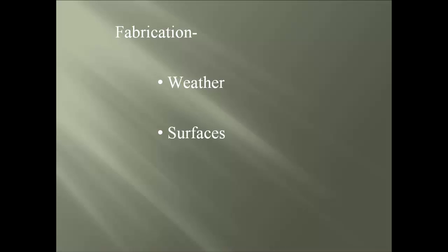Base metal surfaces are next, which should be free and smooth of cracks, tears, etc. that could affect the quality of the weld assembly. The third item is the joint, which should be arranged for the most favorable positions to weld. That includes the base metal being brought together as close as possible for complete fusion. And lastly, another quick tip is if the backing material satisfies ASTM A109 temper 3 or 4, it can be used without a qualification test.